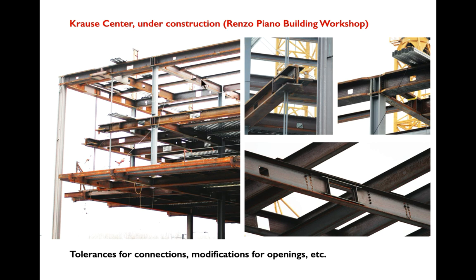Really big ones will be framed so that the forces in the beam will kind of flow around it. But small elements that are placed close to the center or close to the neutral axis of these shapes won't affect the structural performance of the overall beam very much. We saw this when we looked at beams as a structural type.